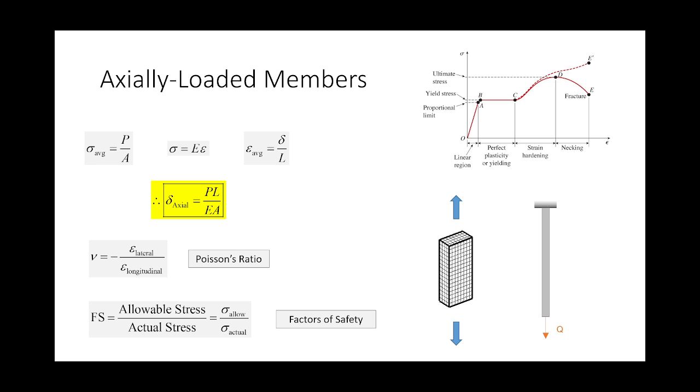what's called elastic response. And what elastic behavior means is that if I apply load, it deforms, but if I let it go, it snaps back to its original shape, just like a rubber band. If I take a rubber band and stretch it, it deforms. Let it go, it snaps back to its original condition. And more often than not, we prefer that in our engineering systems because we don't really like permanent deformation.